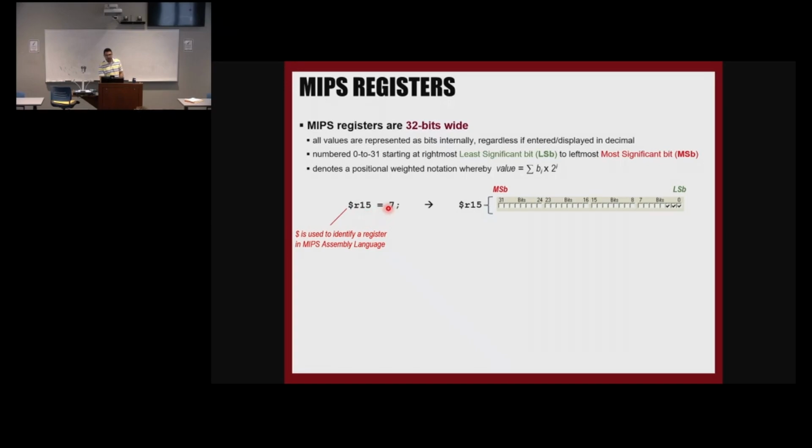and value 7, you see that these bits are 1, 1, 1, and everything else is 0. We have 32-bit registers, even if we don't use them. So with registers, you can't use part of them. You can't say, I just use a byte. You either use the register or don't. You use register T1 or register 15. You can't say use the first half of register 15. Right? But with memory, you can say that. With memory, you can say just load 1 byte. But when it comes to the register, it's 32 bits. It uses the entire 32 bits.